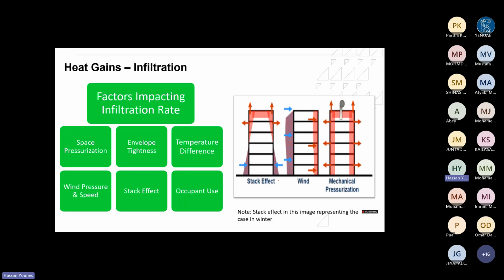So as you can see, a lot of different factors to consider, and one of the toughest parameters to look into and figure out is the amount of infiltration, because of all these different things. How tight it is, I don't know. I could assume something and hope that it will happen in the future. But even if you have the testing done, you wouldn't know exactly what that crack is and on what wall and what orientation. So again, it's a little bit difficult to do infiltration.